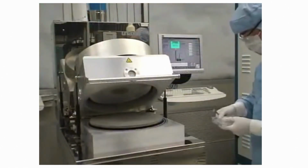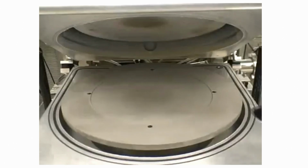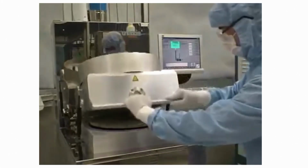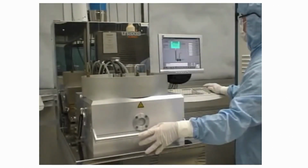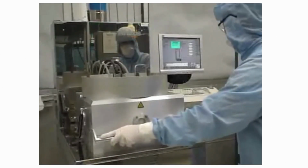Once you have finished cleaning, you may load your sample into the center of the chamber. Once your sample has been properly positioned, you may close the chamber lid and prepare to pump the chamber down. Before running a recipe, you must first pump down the chamber. In order to do this, you must open the Utilities drop-down menu and then select Pump Chamber. Hold the chamber cover down until the rough pumping is complete.